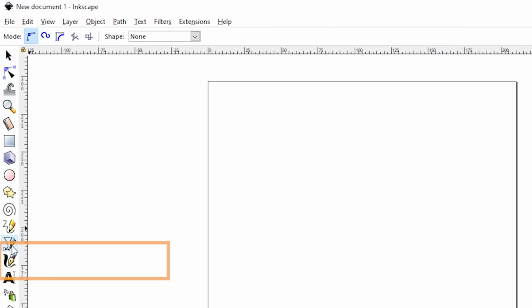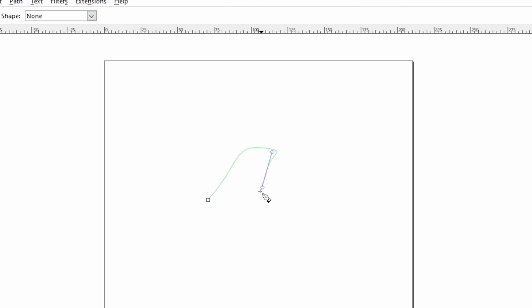So I've got the pen tool here over on the left-hand side, and that's going to draw some interesting enclosed shapes. Now, they do have to be enclosed. That's really important, because if they're not, then Fusion won't know what to do with them, because you can't create solid bodies from 2D lines. It's 0 thickness, which is not great.